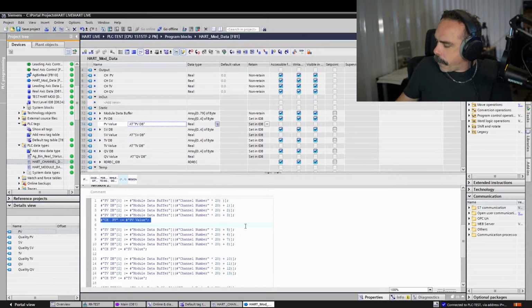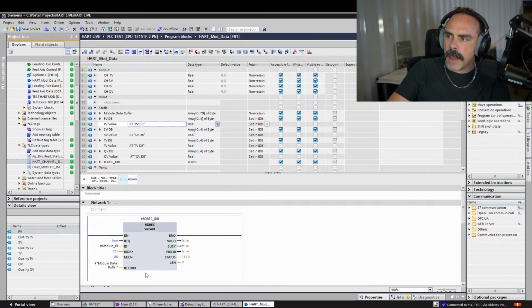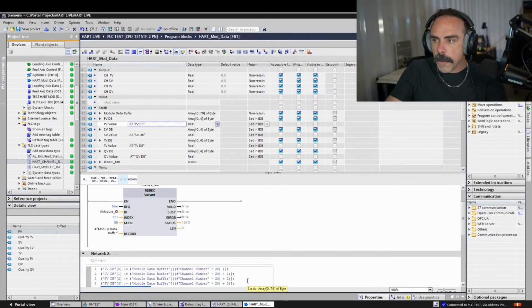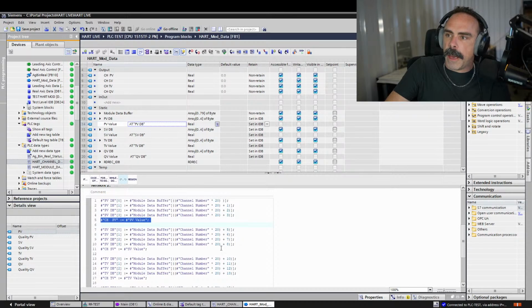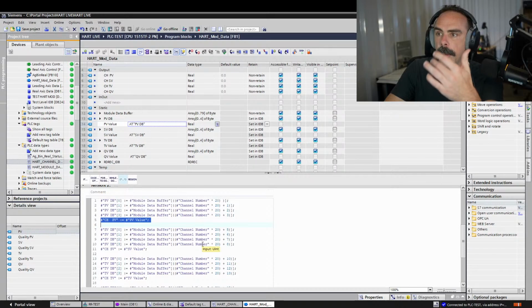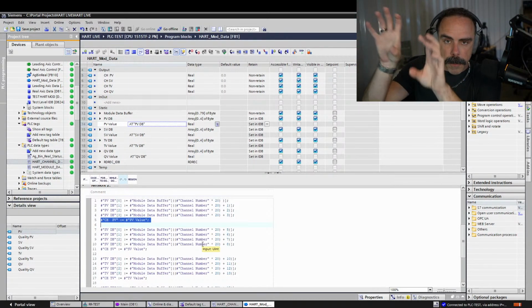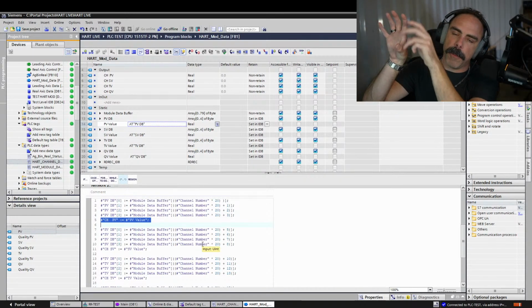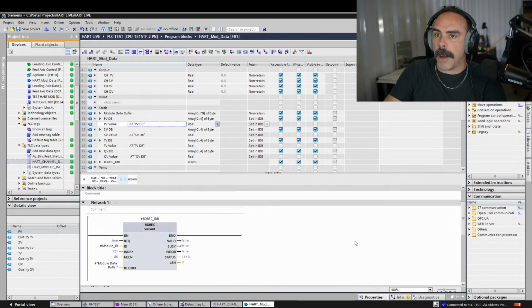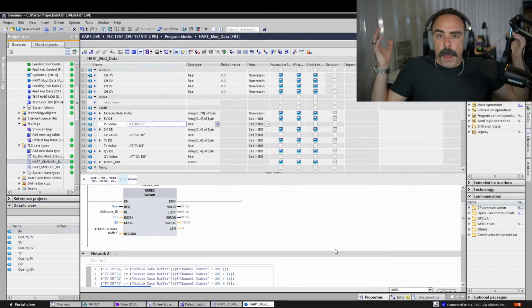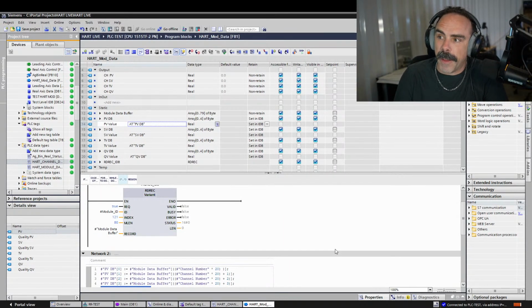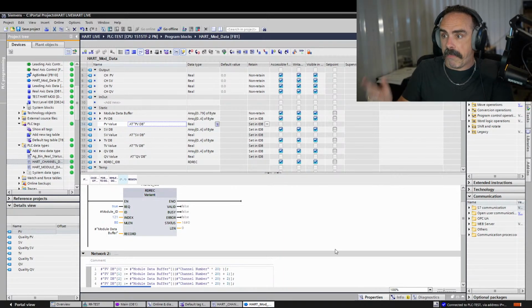And so what I did was go through, and for each one of these values, I have an offset. Again, remember, I have an input that's the channel number. I just have an offset. So like whatever my channel number is times 20 plus 5, and then I'm moving all of those bytes over into the smaller byte buffers, and then overlaying a real on top of that and moving that real out to it. And it sounds complicated, and I know how I would have done this in Classic Portal. This is how you have to do it, and it's obnoxious.